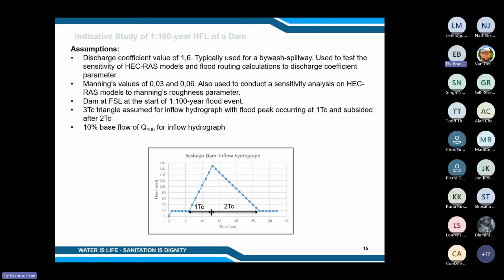If no information is provided regarding the discharge coefficient of the spillway, the most conservative approach would be to perform your hydraulic calculations and hydraulic models for the lower and upper bound values given for the specific spillway, and then do a sensitivity analysis to assess the influence this parameter has on your analysis.